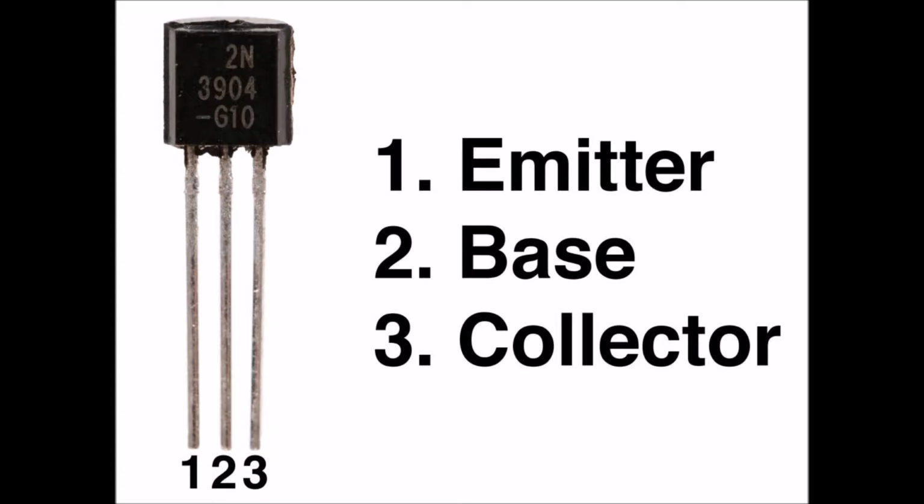Two configurations exist for bipolar transistors: a p-type layer between two n-type layers, called NPN, or an n-type layer between two p-type layers, called PNP. NPN versus PNP. Figure 22.1a is a simplified drawing of an NPN bipolar transistor, and Figure 22.1b shows the symbol that engineers use for it in schematic diagrams.